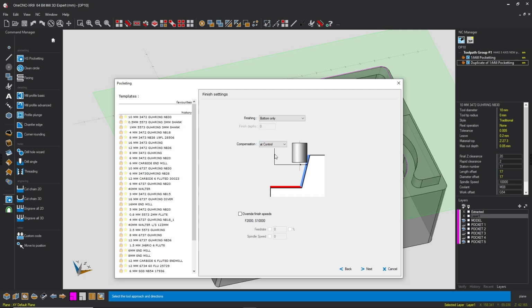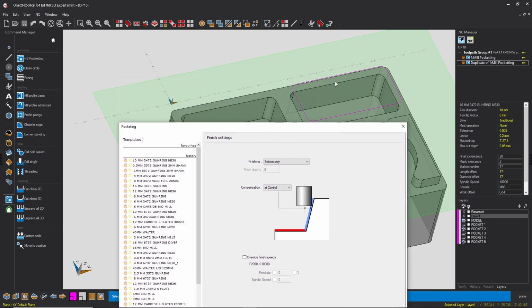So that's what automatic does. At control is where, for instance, you set your offset in your offset page on a Haas machine. You've got your height, then your height wear, then your radial offset, and then your radial wear. Or if you've got it set to diameter, diameter and diameter wear. So at control, it will program to that line and hope that you've put, for instance, this 10 mil as a 5 mil offset if you're using radius, and it will program that as Y -5 on a G41 line.